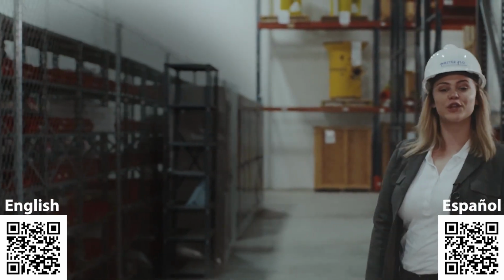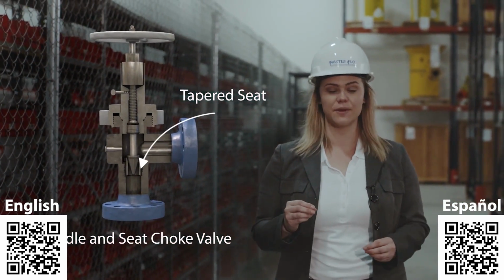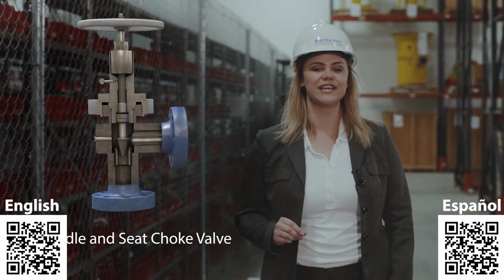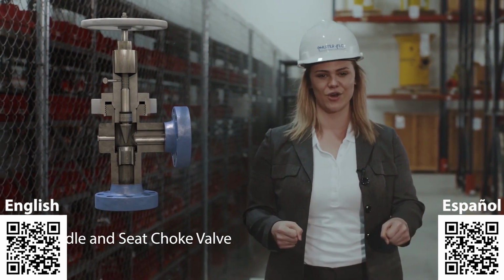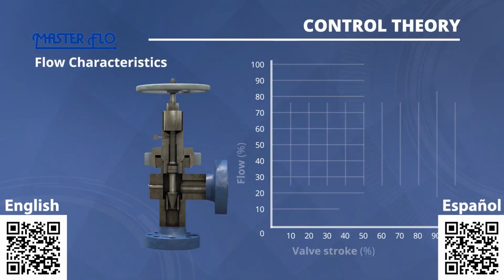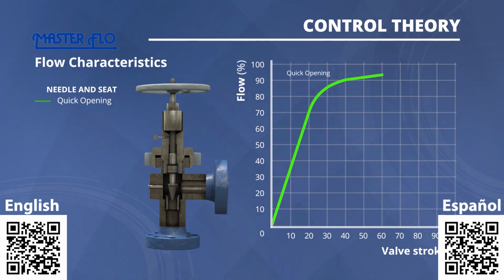Let's discuss the flow characteristics of 4 types of choke valves. The needle and seat has a tapered lead on its stem to restrict the opening by closing the tapered seat. The throttling is achieved by rotating the handle on its rising stem. Due to the tapered design of the needle, a small rotation of the stem handle can cause significant change to the orifice opening. This choke design doesn't provide a high degree of control. When the choke is open halfway, you experience full flow, losing most of your control.